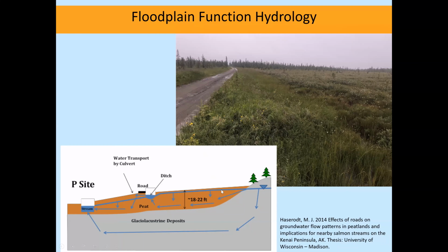the road itself. And they wired up this thing with all kinds of barometers and stream temperature loggers, and were able to see that this peatland's shallow groundwater, that Sean was talking a little bit about yesterday, ended up getting captured by the ditch of the road. And then when it entered that ditch, it warmed up in the sunshine and all that. So it went from groundwater to surface water, and then traversed through those culverts, ended up back in the stream channel at temperatures that were not as ideal for juvenile salmon.